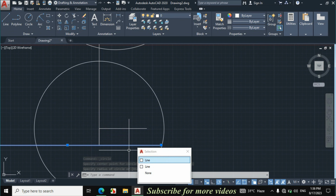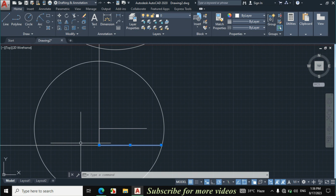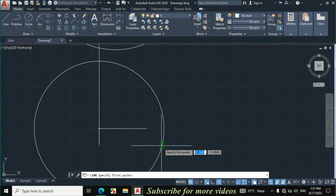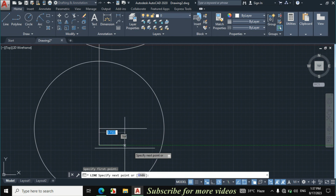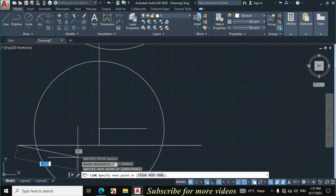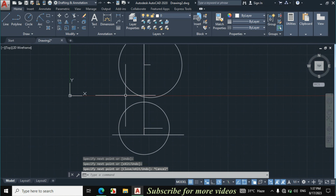I will erase this line, both these lines, erase, click again on line. Now I will make a line which intersects the whole circle. Escape. Now I will make this fillet.